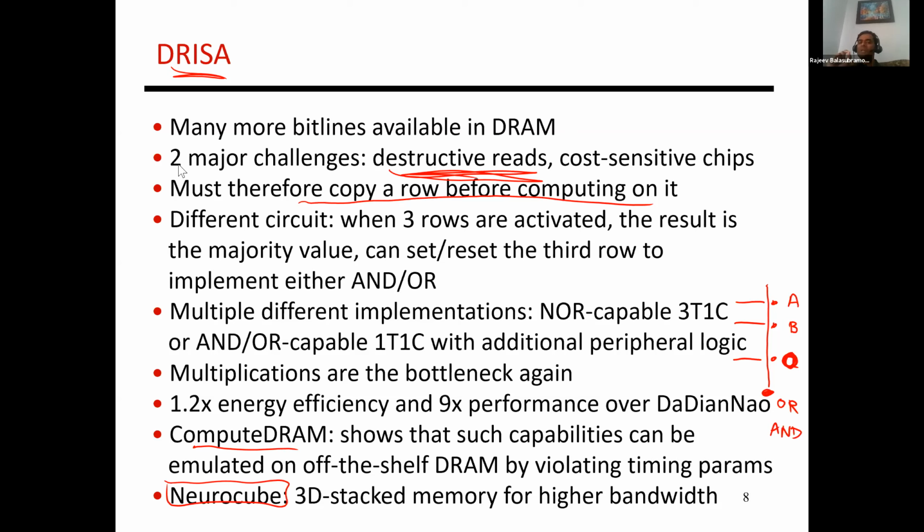Putting in-SRAM capabilities in can allow that general purpose CPU to turn into an accelerator. You could also apply that same concept and say that even on a Google TPU, you have a 24 MB SRAM cache sitting around. So imagine what more you could do if there were these in-SRAM operators inside that large SRAM. But I think most of the time people talk about taking an existing CPU and converting it into an accelerator. But I think that concept is generally applicable in both cases.